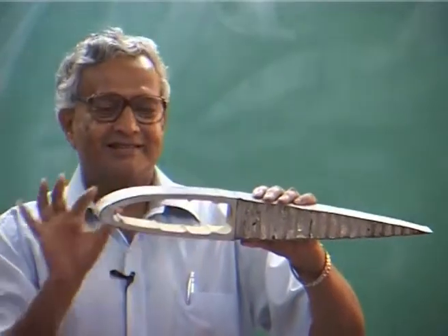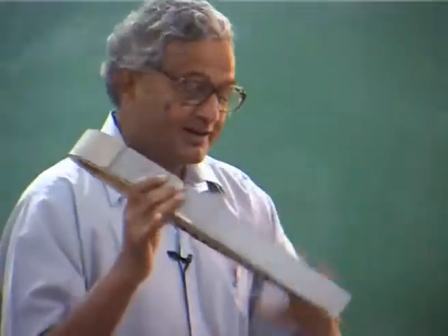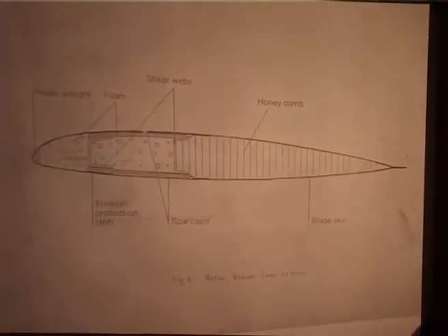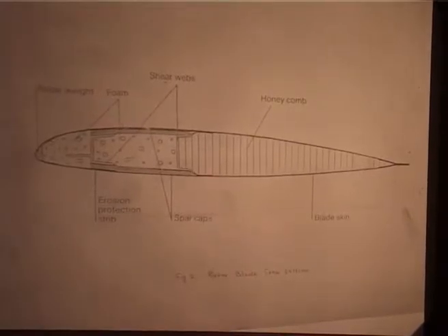So, this whole design is made in such a way that... I will show a typical section of a rotor blade, just similar to this. Okay. Only thing is each blade has its own section. This is the real life actual blade cross section. You always put a leading edge weight, that is to shift the center of mass to 25% chord from aeroelastic considerations. Okay, we will learn that.